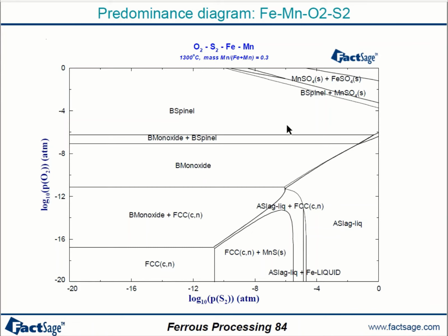We have run those kinds of things in even engineering thermodynamics. Probably some of you have done this kind of phase diagram for the pure iron, for example. And in the phase diagram module, you can include both pure stoichiometric species plus all the solid or liquid solution. That's the power of the phase diagram calculation for the predominance diagram.